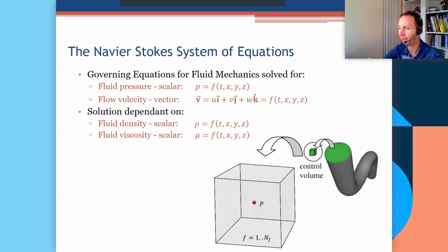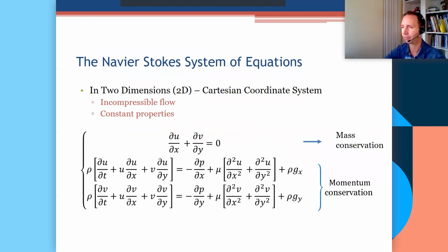So essentially you have to think of, you pick a small volume in space anywhere. For example, this cube. Using a cube is convenient because it means the faces are aligned with the coordinate system axis, X, Y, and Z direction. So you pick a cube, you've got a point at the center of that cube, and you can see how the flow variables change over that cube in order to derive from first principle the governing equations. Let's go to the next slide.